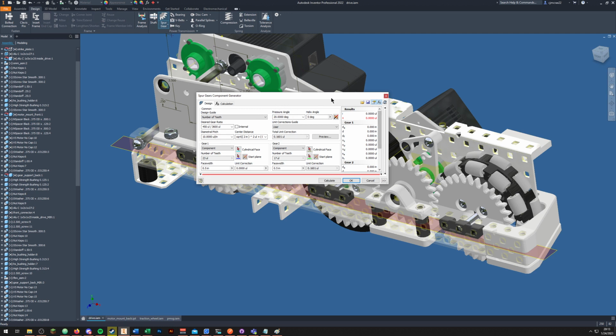For the most part, you don't have to worry about a lot of these things. We're just going to be looking at this upper left hand corner. Quickly, just before we get started, there's a lot of different settings here, so we'll start with what they all mean. Here you can see it says diametral pitch or module. Diametral pitch is the imperial way of specifying tooth size, where module is the metric way, and they're inverses of each other. So a high module would be a low DP, and a low DP would be a high module.